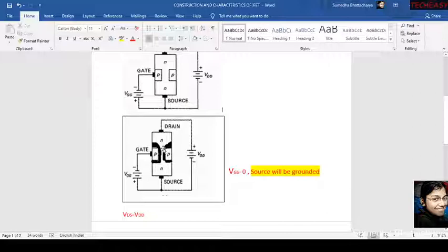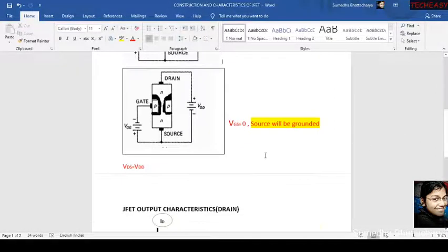Why is that the reason? I hope you all understood. Because of the depletion region, this region acts like a resistance for the current. This resists the current from flowing from drain to source. For this reason, at a certain voltage, the current will be saturated, and after that the voltage will be increased, but the current will not increase anymore. So it is about the construction.